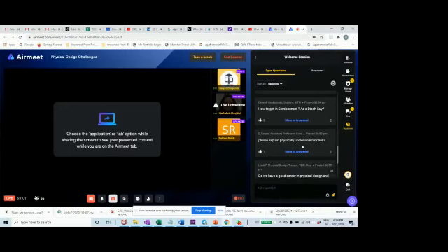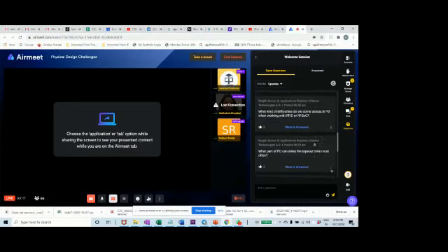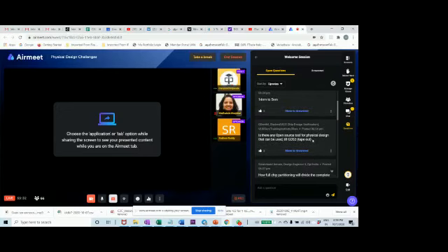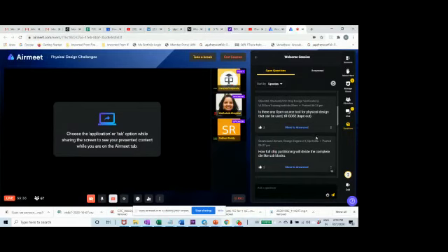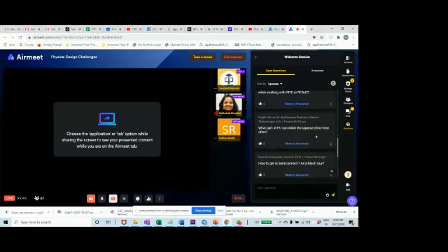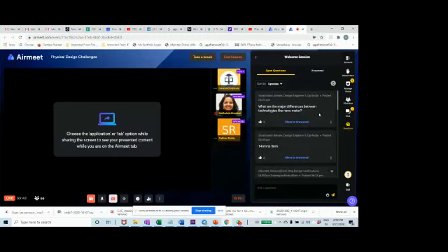Okay, please explain physically unclonable function. So, for example, if you have a design which has to operate at different operating conditions, then most of the design is physically unclonable. In fact, if you look at any cloning that you do, any gate, if you look at exact physical parameters, for example, input transitions, output transitions, the way power supply is given to that particular gate, all of that will be physically different. It's the same AND gate, but if you are placing it in different places in the design, it will have different operating conditions. So, in that sense, even though it is a logical clone, physically they will be exclusive entities.